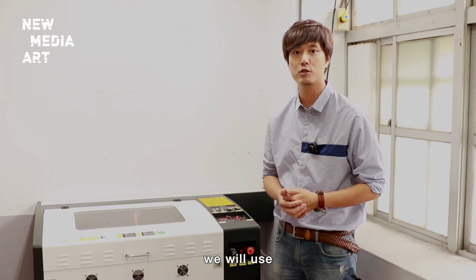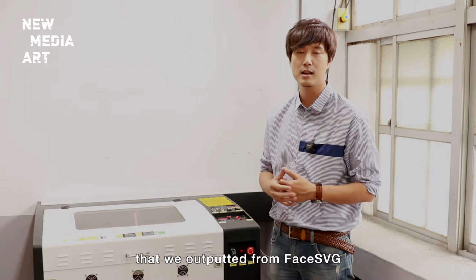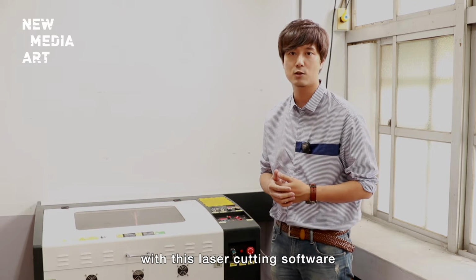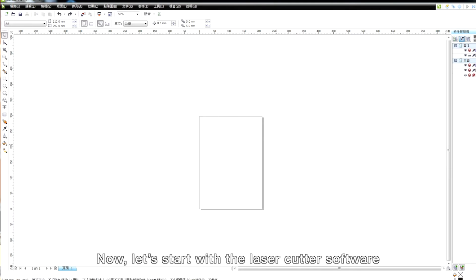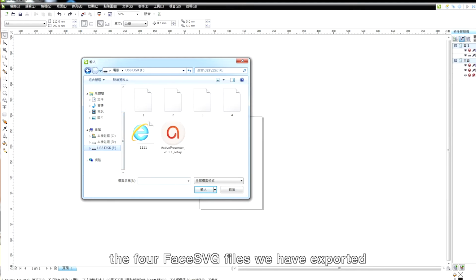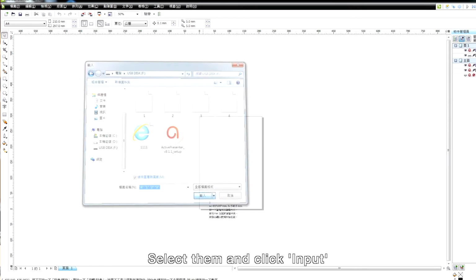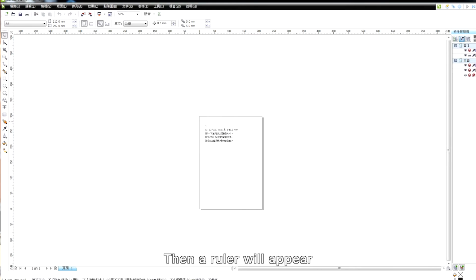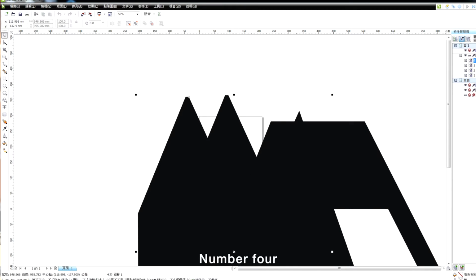In a moment, we will use the vector graphic that we outputted from Face SVG with this laser cutting software and explain to everyone how to do this. Now, let's start with the laser cutter software. First of all, we press Input in File. Here we can start from the 4 Face SVG files we have exported. That is the vector graphics files. Select them and click Input. Then a ruler will appear. Let's move them in. Number 1, number 2, number 3, number 4.